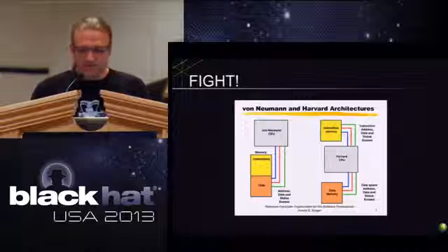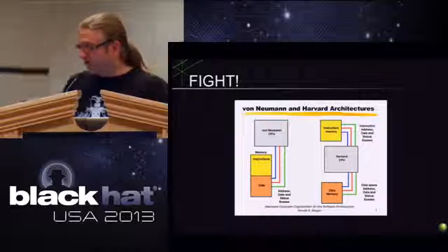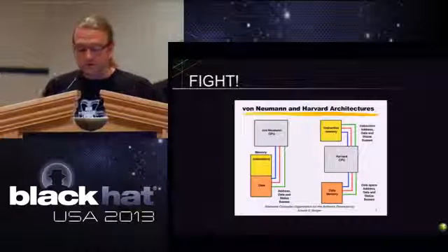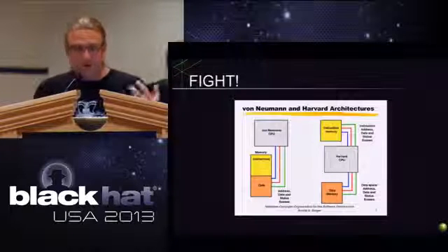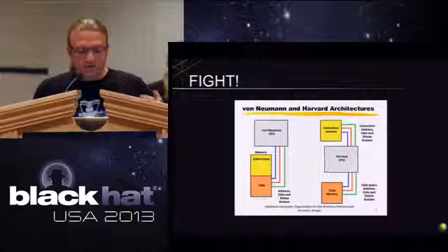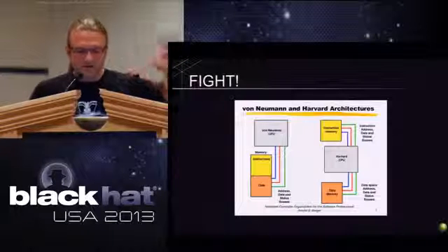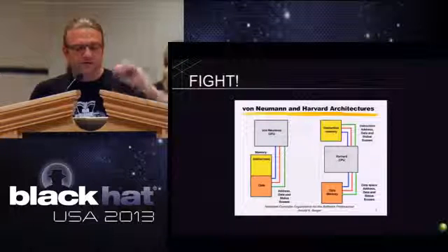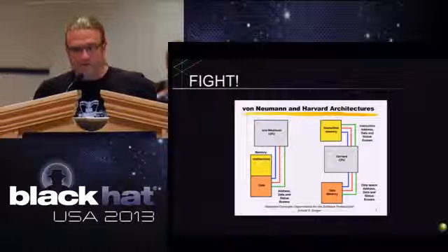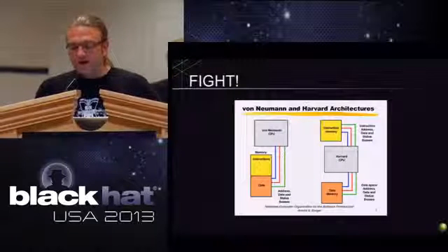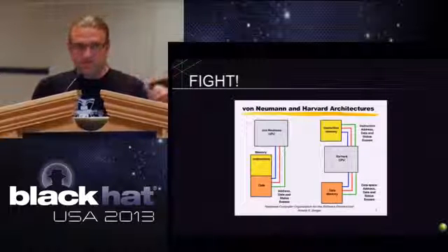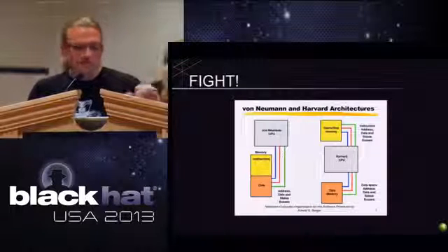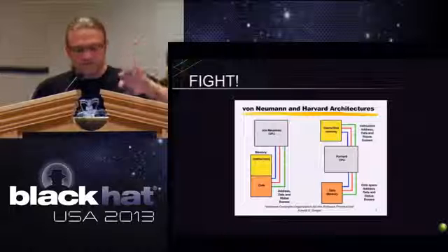And we have Harvard. So when we're dealing with x86 or old ARM or things like that, we're typically looking at von Neumann architectures. When we look at von Neumann and how it works, we're used to having a code section and a data section. We're used to the CPU being able to grab between them. You may have tricks like NX and stuff, but that used to be only software. Now it's software and hardware, but it's an add-on.